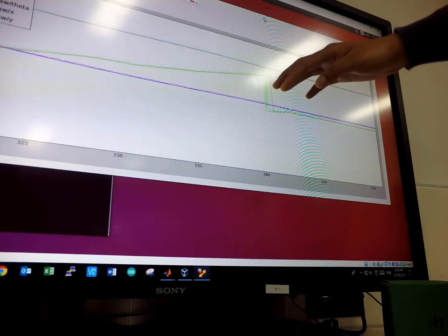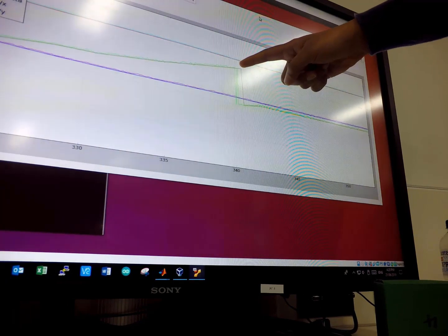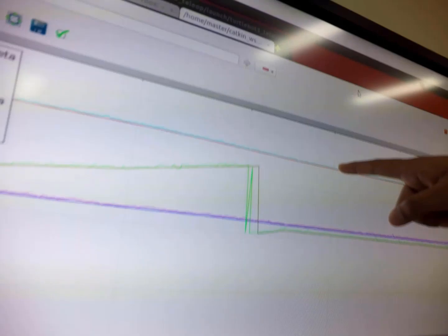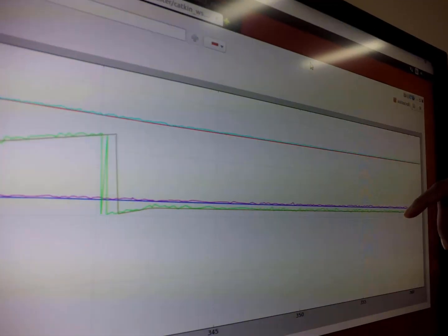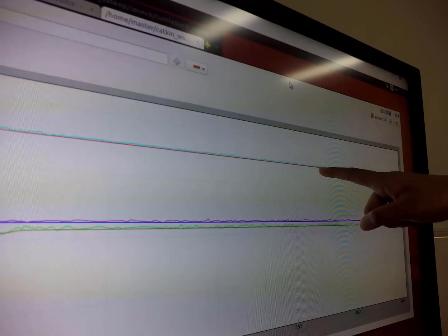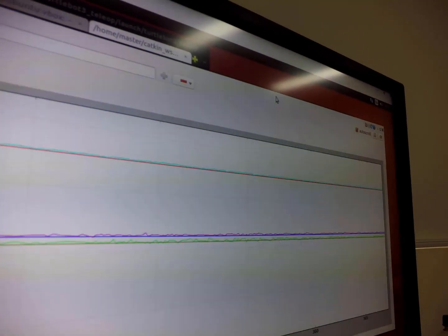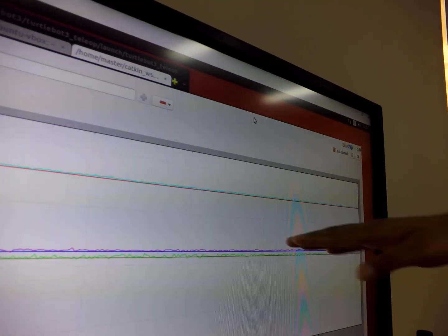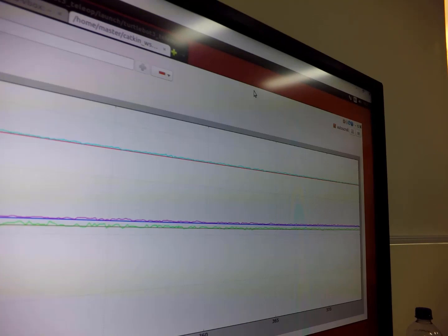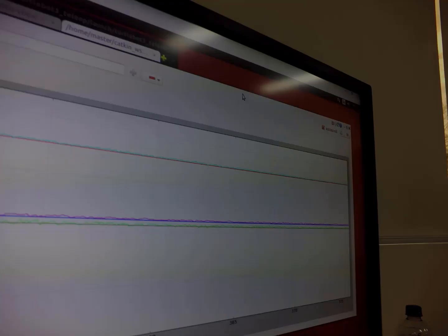So basically the EKF estimates are now really close to the Vicon estimates. Yep. The Vicon estimates are treated as the ground truth, and the EKF graphs, which are the brown, blue, and the red, are acting like they're smoothing out the errors in the Vicon data. So that's what the EKF is meant to do.